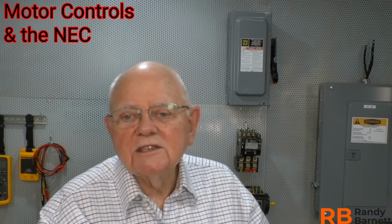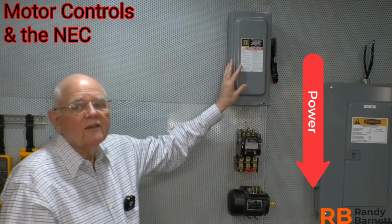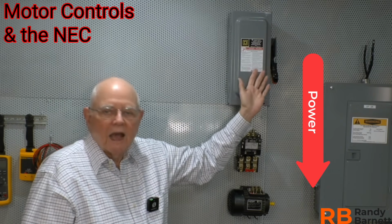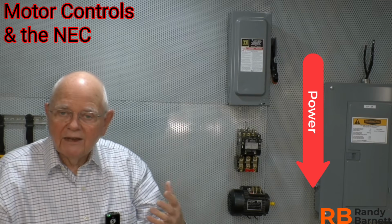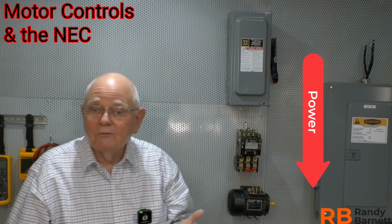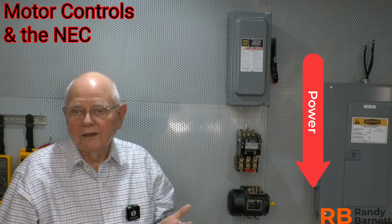So let's take a look at the main components on the first circuit, and this is our main power circuit. For the main power circuit, I start up here and I have to have some type of disconnect, don't I? I've got a requirement in Article 430 about having a disconnect within sight of, meaning within 50 feet and visible from, the motor that I'm controlling.